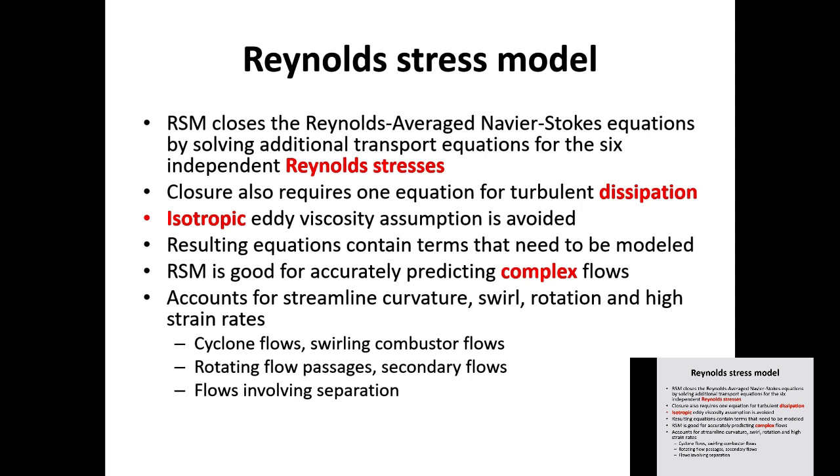Reynolds stress model is better. Okay. In your T-pipe problem, you didn't have swirling flows, so the flow was fairly simple. You don't really have to go to the Reynolds stress model. A K epsilon or a K omega model would be good enough if you had a good mesh. Okay.